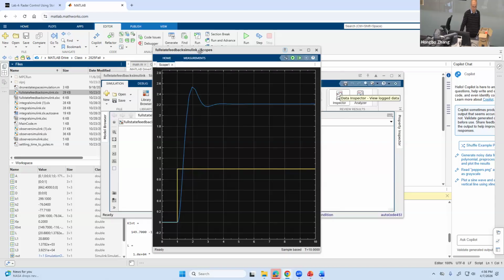You can see, guys, that means the full state feedback control actually works. Why does it work? Look here. The full state control here, you can see this one is the step input, and this is your step response. You can actually control it, although there's a pretty big steady state error. That's the problem with full state control, because it does not consider an integral part. It's mostly PD control, by the way, because it does not consider the output.